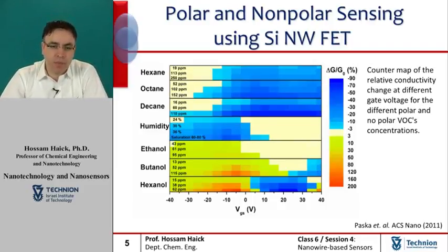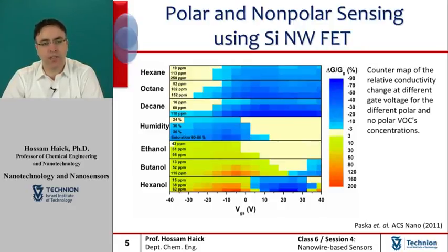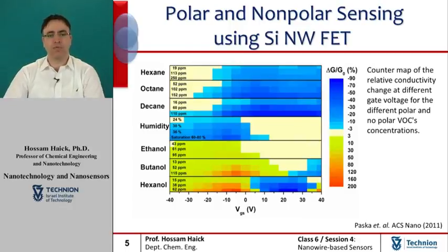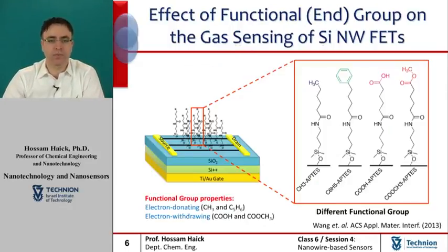In support of this claim, we have observed negligible responses of the bare silicon nanowire field effect transistor sensors upon exposure to non-polar volatile organic compounds, and non-stable and non-reproducible responses upon exposure to polar volatile organic compounds. In spite of these improvements in the use of molecule-terminated silicon nanowire field effect transistors for gas applications, the mutual relationship between the molecular layers and the volatile organic compounds or gas analytes is still a puzzle.